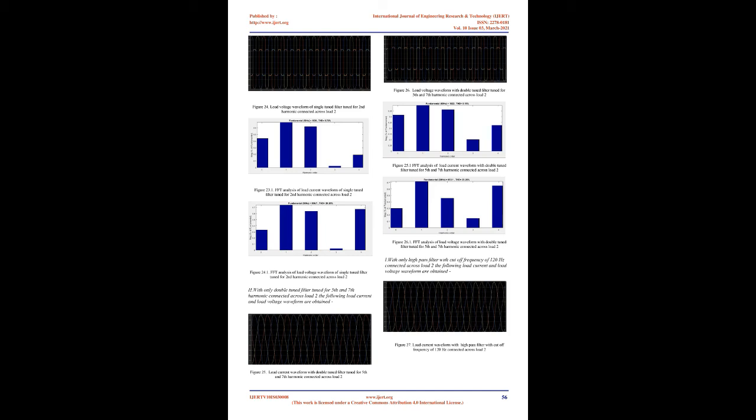Methodology. The simulation is performed in Simulink, a registered trademark, with time of simulation being from 1 second to 2 seconds. The solver used to simulate is ode4, Runge-Kutta, with step size as fixed. The format for input and output data is set to array and maximum number of data points is set to have a value of 1000. All the other solver parameters contain default values.